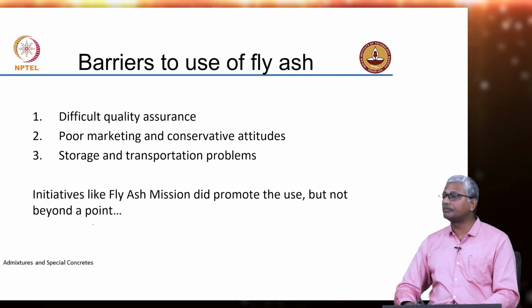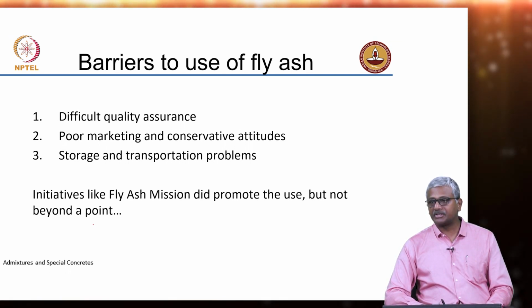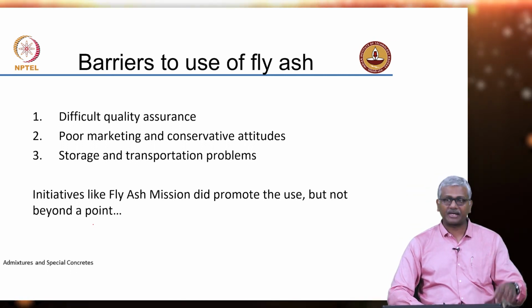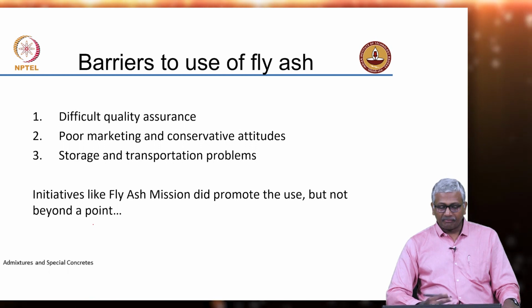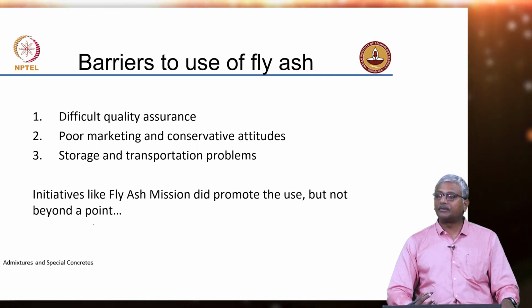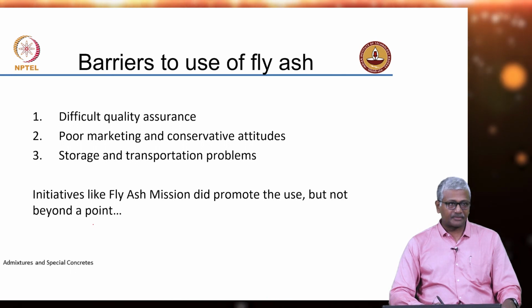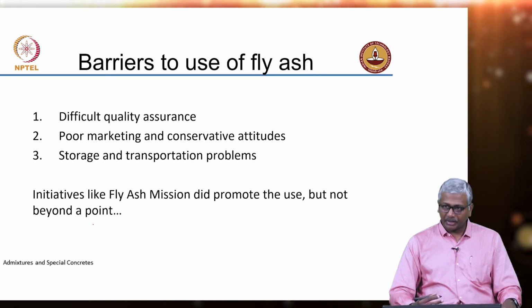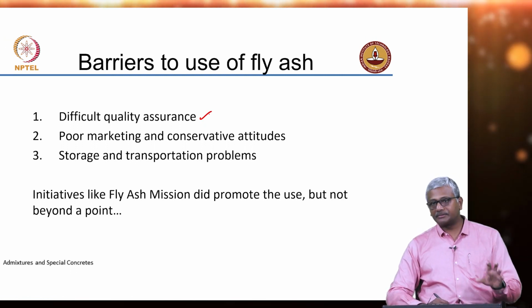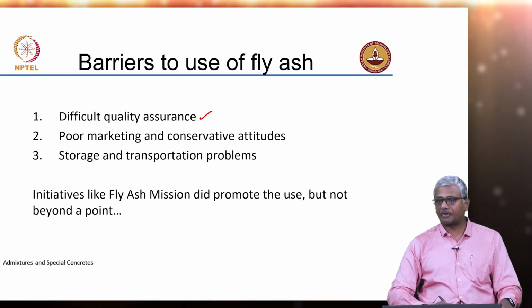Storage and transportation problems can also happen, because excess moisture may be absorbed by the fly ash and you need more storage space in your RMC plants. You need to have an additional silo for fly ash storage and so on. Fly ash mission was an initiative undertaken by the government to promote the use of fly ash, and that really worked well for several years. Okay. But again, unless we overcome this issue of quality assurance, the fear in the minds of the consumers will always be there that you will not get a consistent performance with fly ash based concrete.